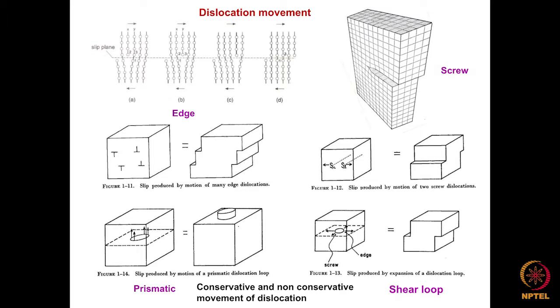Suppose a dislocation moves in a sample from this region to this region, no external shape change will take place. The external shape change will take place only when this dislocation has moved and come out of the sample surface. Then this sample will look like a step has been created, and shape change has happened. We assume there was only one dislocation, and it has just come out. That dislocation has created a step. With that, its job is over, because the dislocation has vanished from the sample.